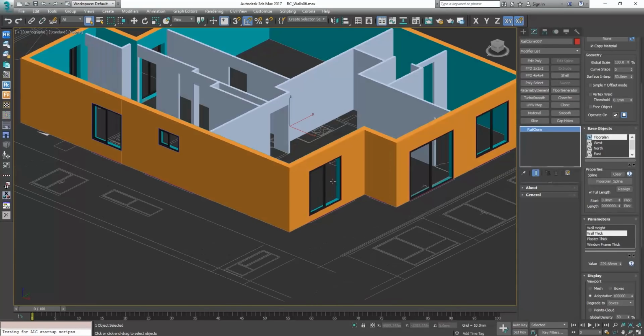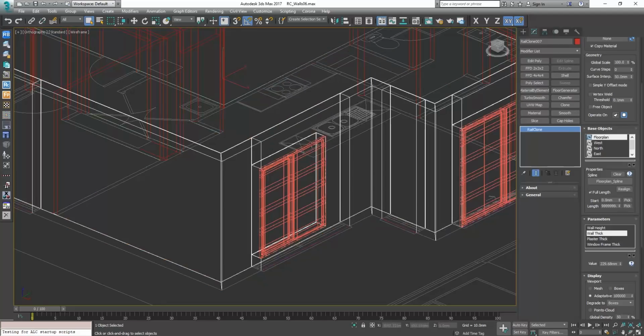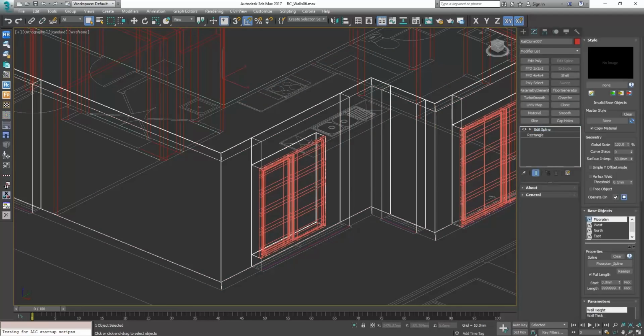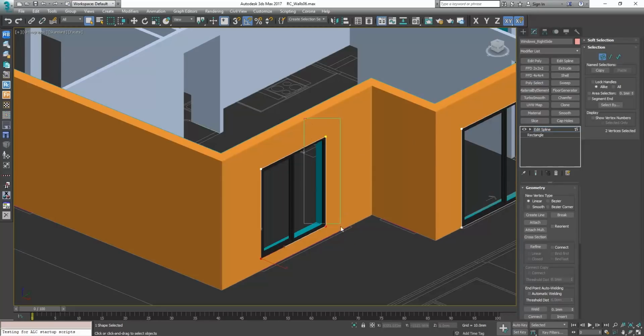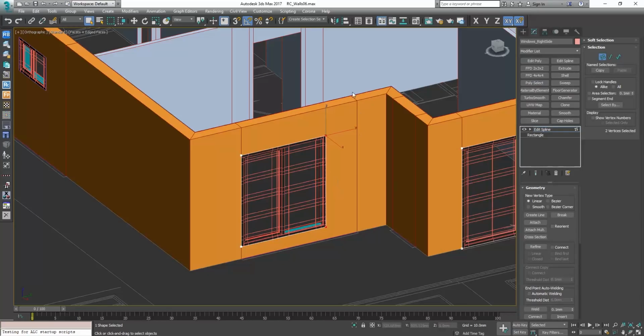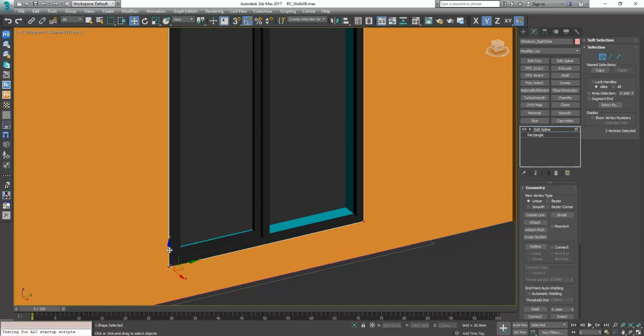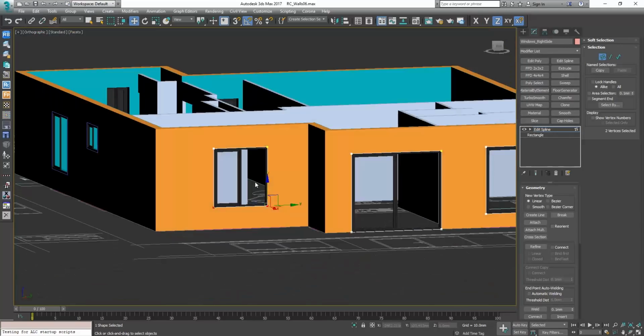Also, we want to be able to have our windows parametric to this wall. So if we have, for example, our spline shape, just take note of the boundaries I've put here. I'll explain this shortly. We can now extend or change the size of our windows, and all the wall will align with it.